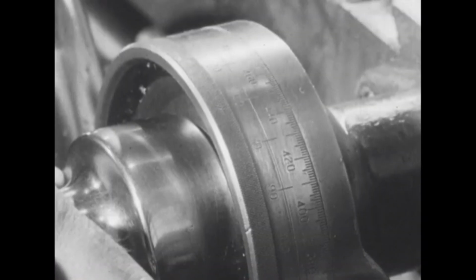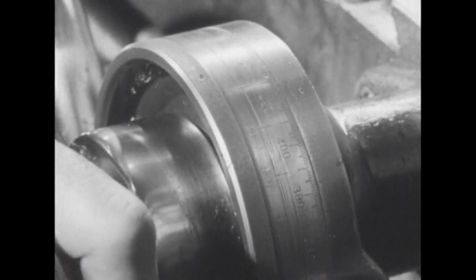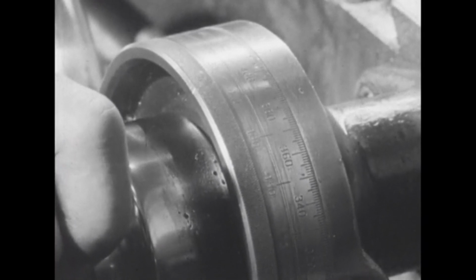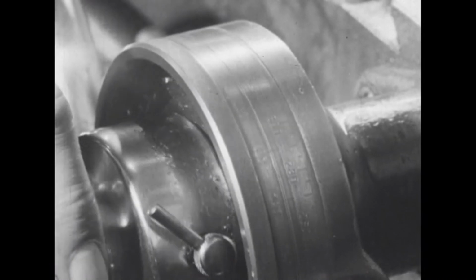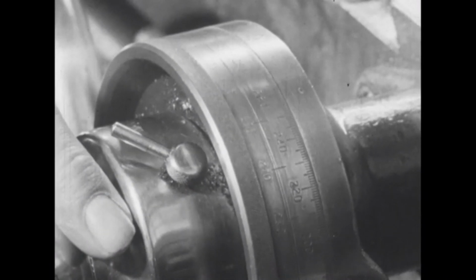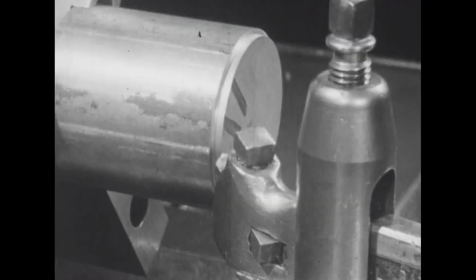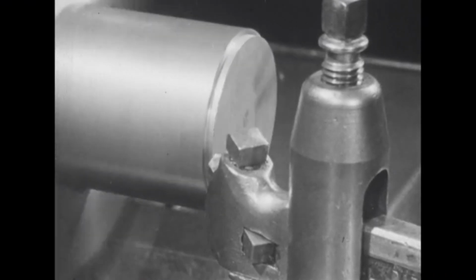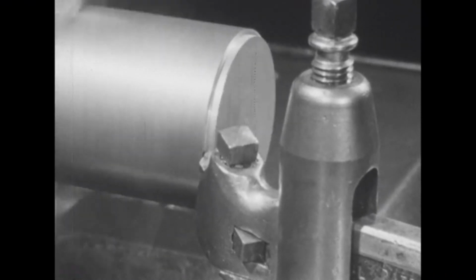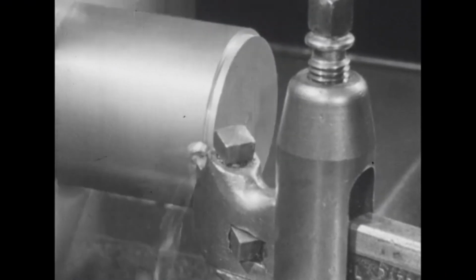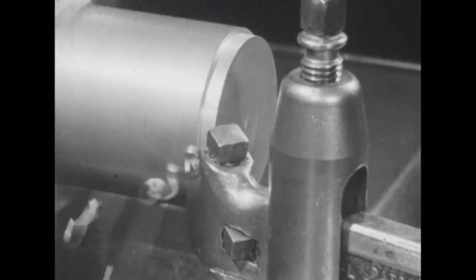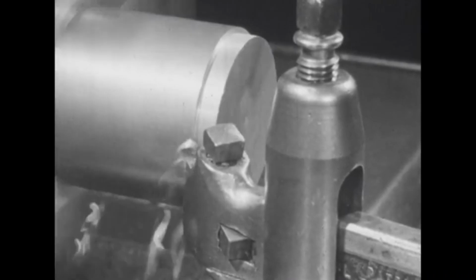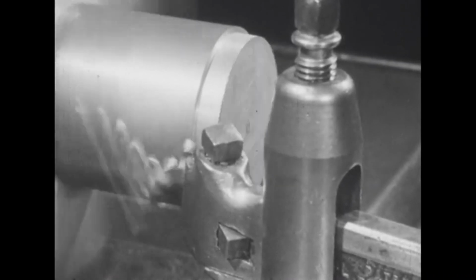The feed dial of the lathe allows the machinist to move the tool bit to within 1/1000th of an inch of the desired depth. The primary object of this rough cut is to remove material as rapidly as possible. Lathe spindle RPM, tool bit, and tool feed have been selected for that purpose, and material is removed to approximate the desired shape of the part.